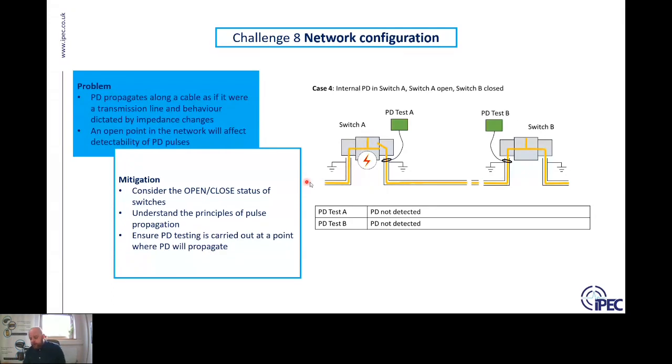Case number 2, as I mentioned before, is probably the most common case. And normally this problem is come across when combining online and offline PD testing. So quite often I've been to site in the past where a customer may conduct an offline PD test followed by an online PD test.